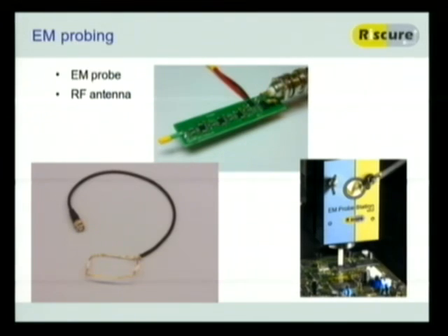But using EM, you can get much better signals than using the RF. I mean, this is actually still more or less a direct power measurement, because the contactless card is being powered by the field. So the more power it drains from the field, the less you're going to measure with this thing. So again, it's more or less a power measurement on a contactless card.